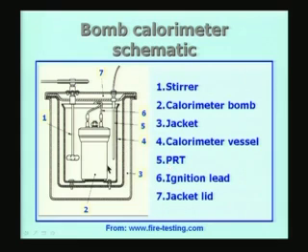So, we will burn a small amount of benzoic acid, usually much less than 1 gram, typically maybe 0.1 or 0.2 grams, in the form of a small pellet like a tablet, and it is burnt completely in the first experiment after filling the bomb to about 25 bars of oxygen pressure. Inside the bomb, we also put a small amount of water, usually 1 cc of water is enough.